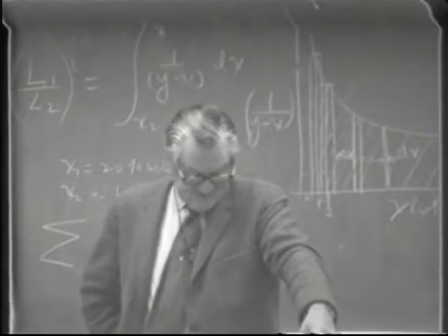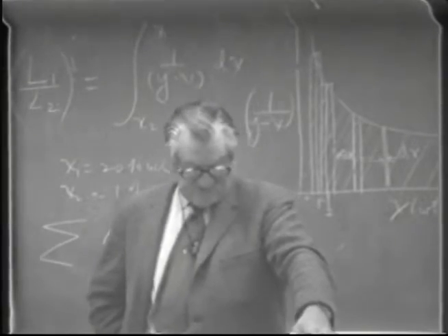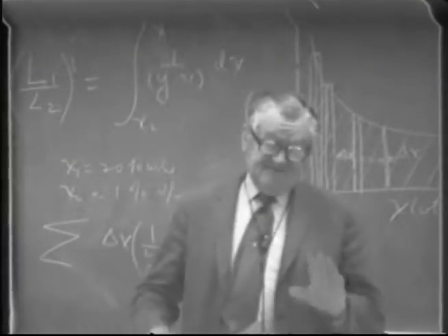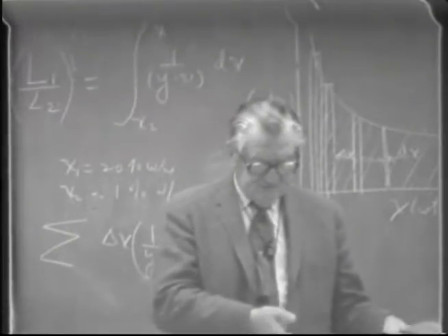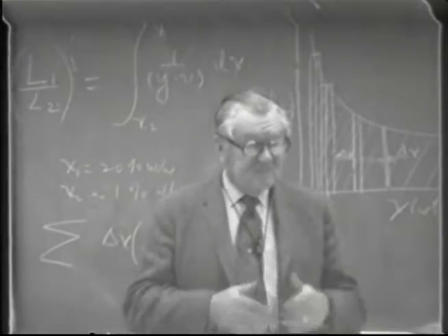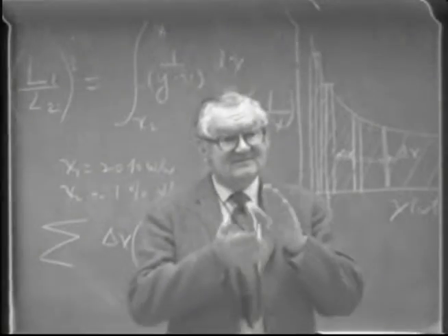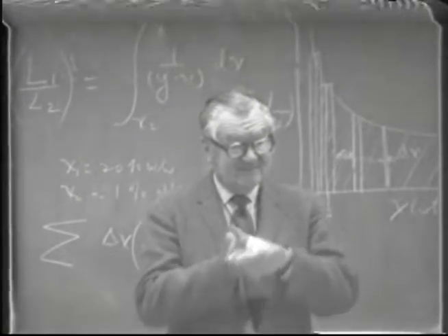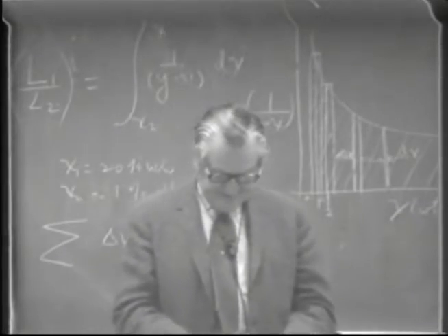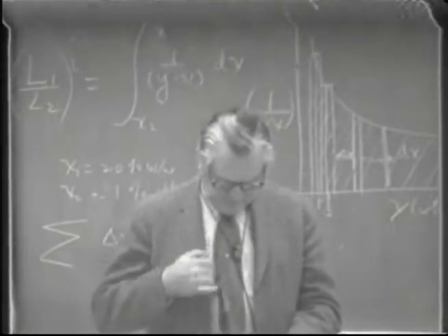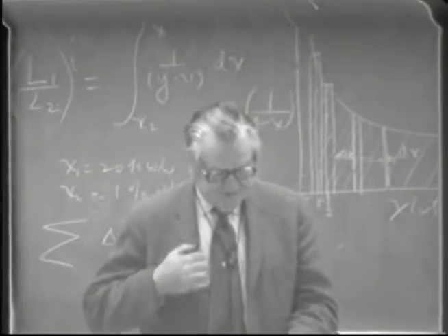I suggest here 24 to 48 hours. This, of course, is sort of a rough conclusion because it depends on the actual holdup of the liquid in the column, how many trays, how much liquid is held up on a tray, and what strength you really try to have before you start it up.